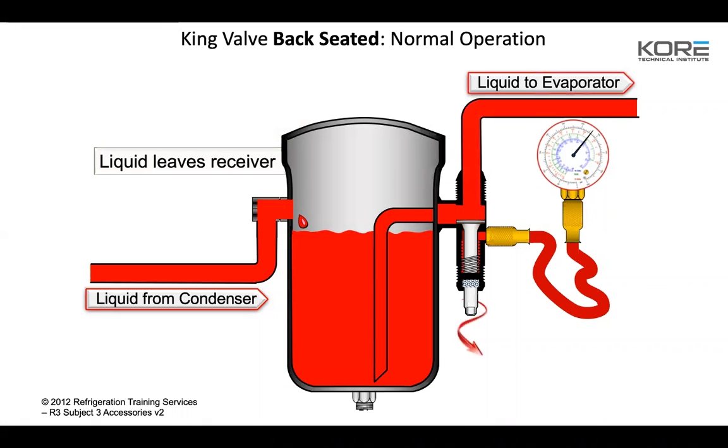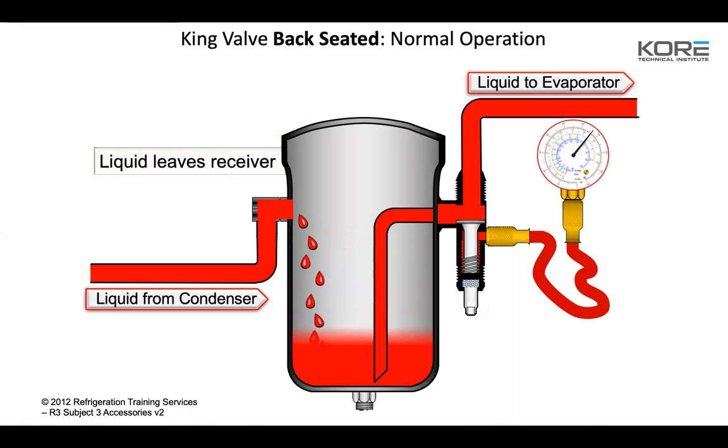And then we back seat it. So if we tell you guys to front seat it, that's always going to be a clockwise turn to run it all the way in. If we tell you to back seat it, that's going to be back seated counterclockwise all the way.